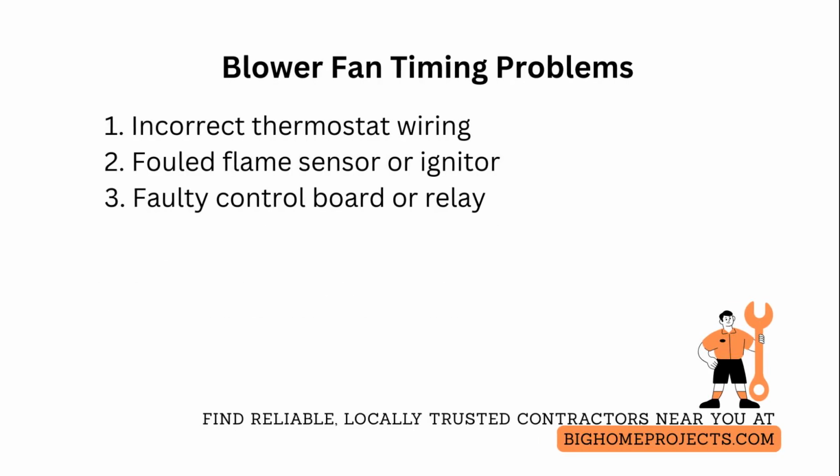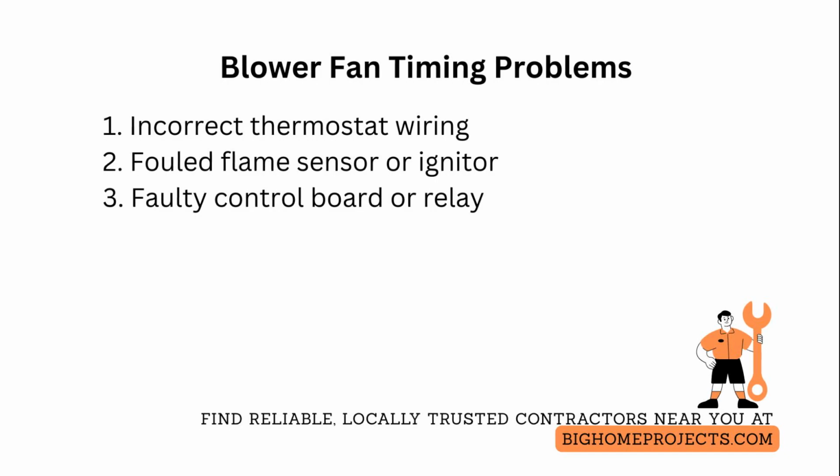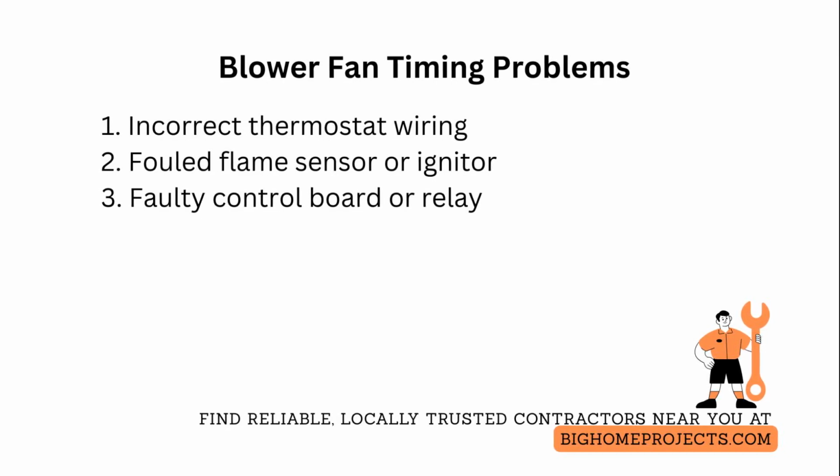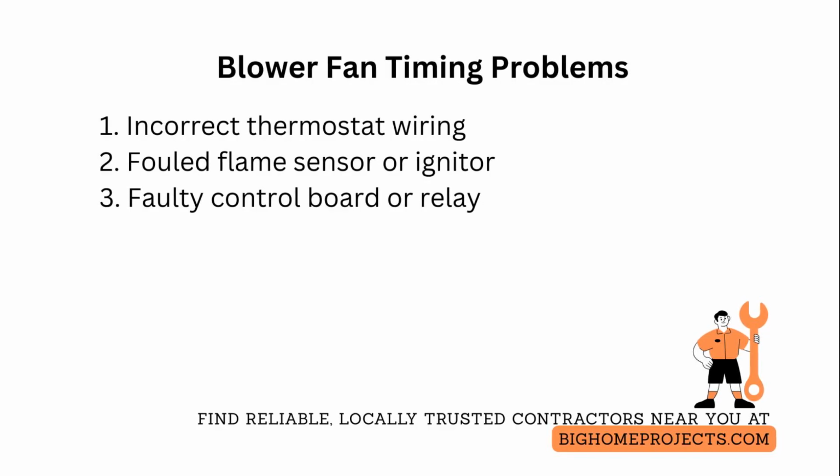One of the most common mistakes is incorrect thermostat wiring causing fan-on issues. Fix by moving the fan conductor to the proper terminal, use thermostat fan settings, set to automatic only, and verify compatibility with your furnace control board.